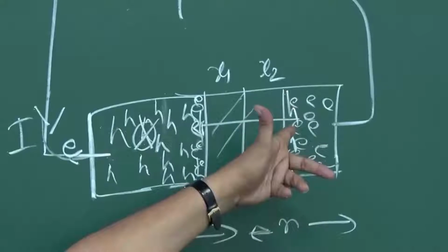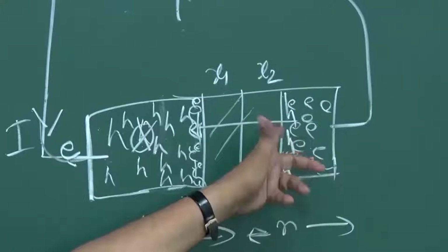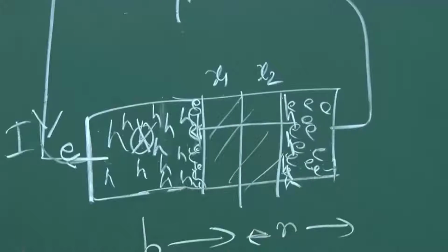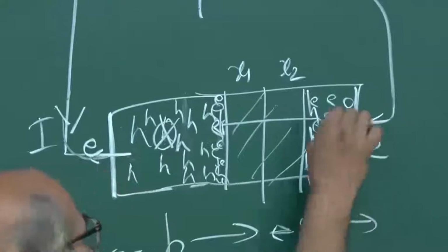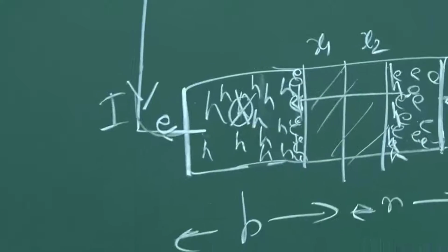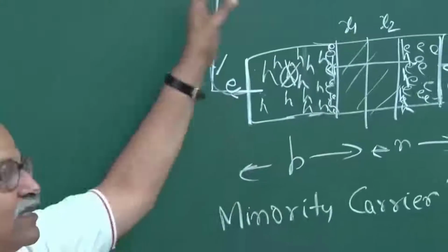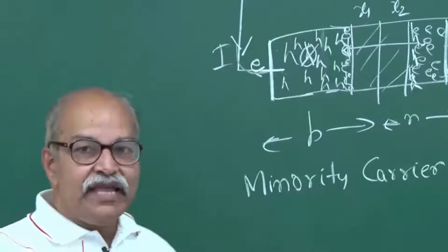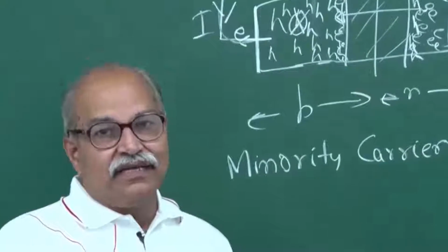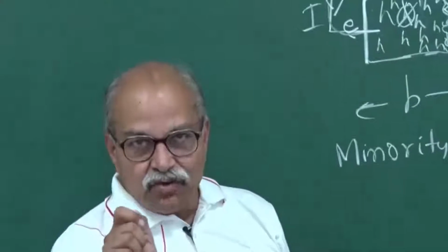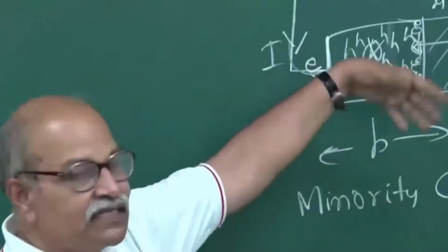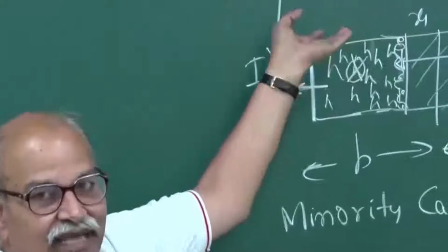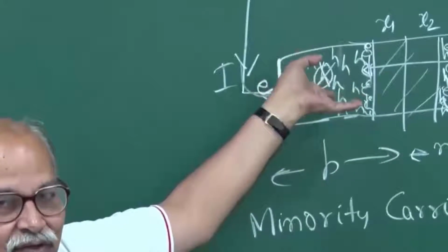And if one electron goes from there, once again negative charge goes, and therefore this circuit will supply an electron through this contact here to compensate that. So that is how the current goes. And all these things are in a controlled fashion. You control that biasing voltage, and then you control all varieties of the phenomena here and the resulting current also.